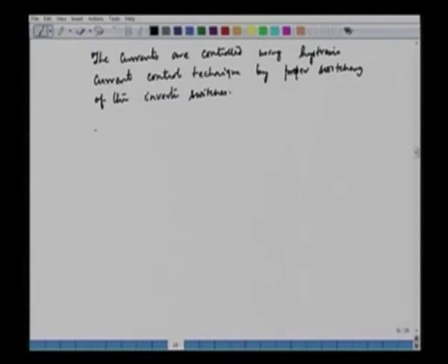So we can just have a logic that if IA is higher than IA star plus H, S1 is turned off and S4 is turned on.